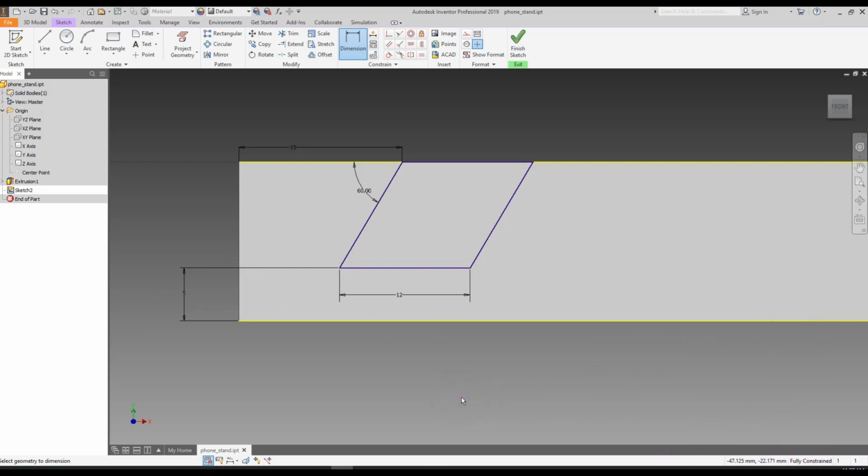And I will show you a little bit of a trick, but it comes with a bit of a warning. Don't overuse this function if you don't have to. Say you're sketching something like this, making whatever design you're working on, and no matter how hard you work, down here it may say that it is still not fully constrained, and you can't figure out what dimension is missing.